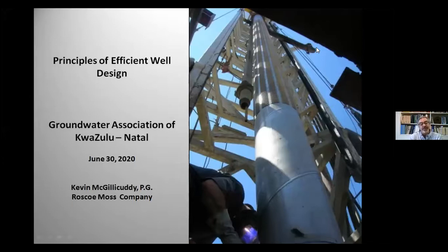What I'm trying to do is improve the overall thought process in water well design, going from strictly, let's produce a structure that's supposed to produce water at a certain rate, to putting a few more expectations on our wells. That's to say we want them to produce with the least amount of drawdown, the least amount of head loss, and the least amount of overall cost to the owner and operator.